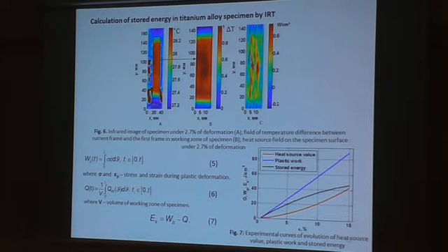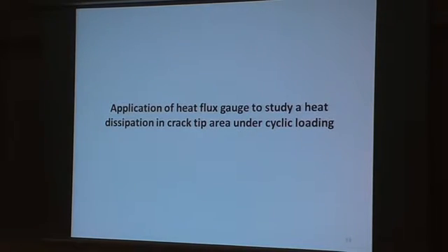And we have, right from our point of view, the constant which describes the environmental conditions, and we can calculate the stored and dissipated energy in our experiments. So on quasi-static tests now we can do it practically for any materials, and we have tested, for example, titanium, Armco iron, and so on. From my point of view, it's very interesting to see what it's possible to take from this for crack propagation. It's very close to the previous presentation, and I want to start.